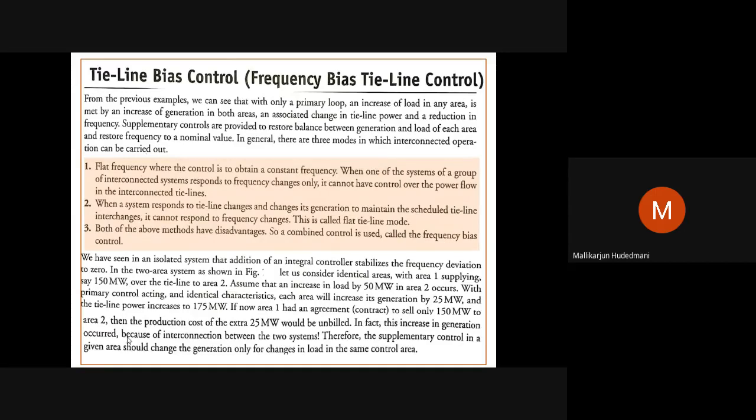What is the compromise? It is going to maintain flat frequency, whatever is set, but it is not going to concentrate on active power delivery from that generator. The rest of the systems are going to concentrate on that. This is a small deviation in the definition or observation when the flat frequency technique is practiced. But this ensures frequency is maintained flat, while that machine's tie line power flow is not controlled.